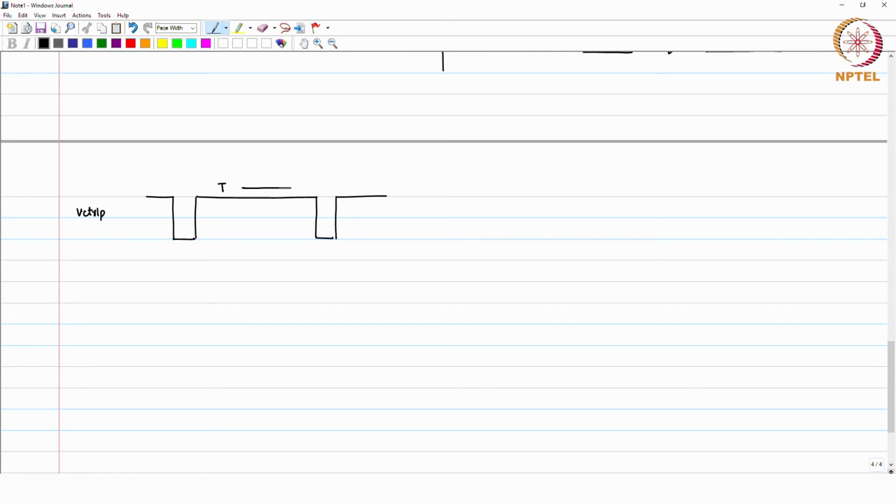Okay. This is your time period T, and for how much time? This is for T offset jump, I_CP times R. You can have a negative jump, you can have a positive jump. So, I can very well say if your I up is lesser than I down, then you may see such kind of jump. There is nothing like you can have only one kind of jump, you can have both positive or negative.